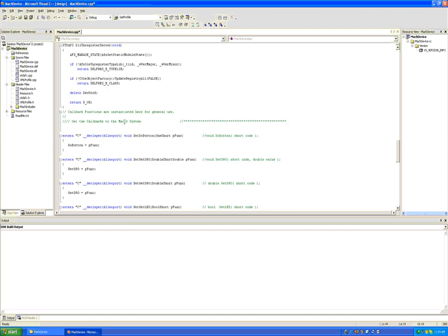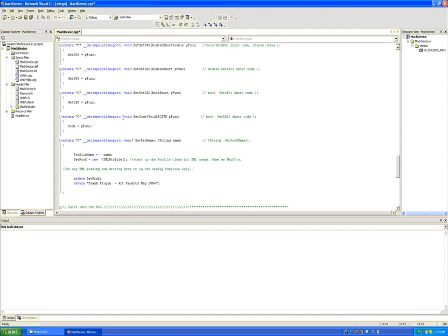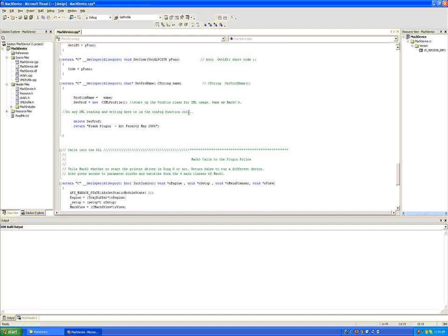So most of this you can skip, write down, and ignore the external specifications that I've made for all of these codes. Again, those are important to the initialization of the plugins. You can do that right down to set pro name. Set pro name is called by Mach3 to set the profile name and instruct the plugin where to store things and get things from an XML profile.